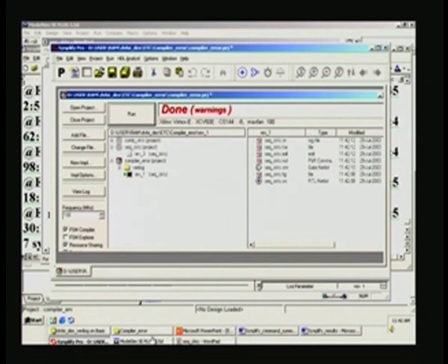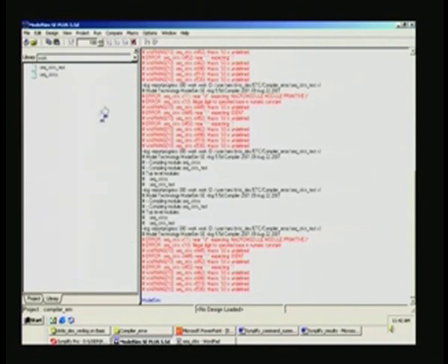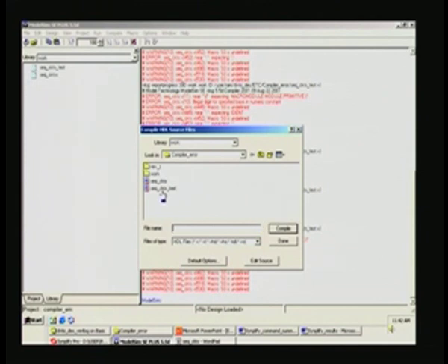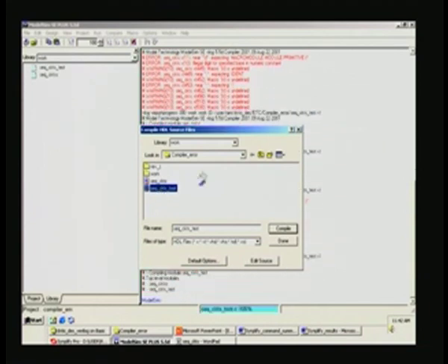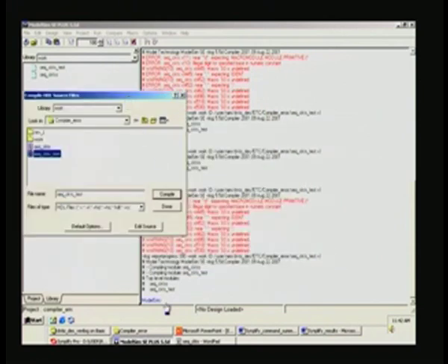So, let us go to ModelSim and find out. So, that is here, and in ModelSim, if I say compile, this is the test bench here which we are going to compile. Let us see what it does. So, I compiled in ModelSim, and fortunately or unfortunately there is no error reported here.